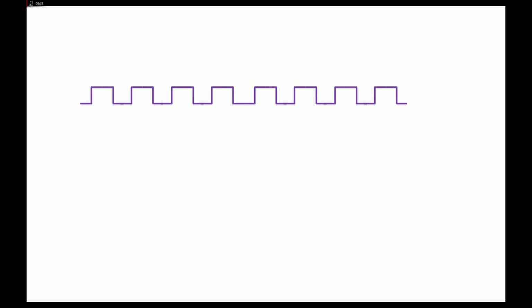So first of all, let me show you how the PWM looks. This is our PWM pulse. This is the on time, then we have off time, on, off, and so on. Now what is frequency in this? Take a look here, one on and one off time. This is your frequency. Like I say, I want to set a frequency of 5 kilohertz, then it will be decided by this, that will be the timing.